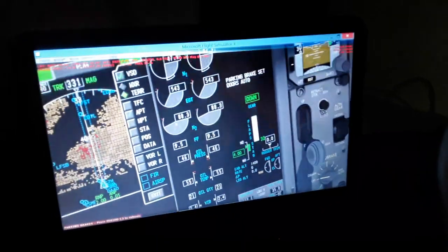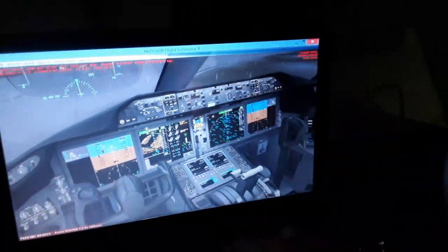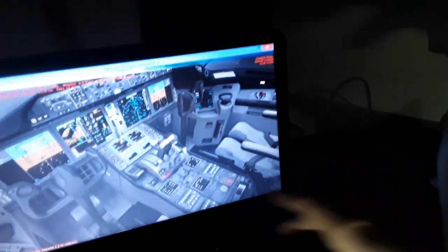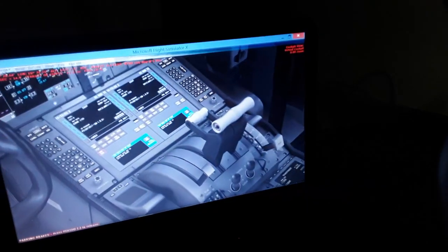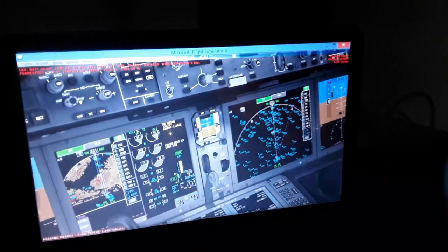The percentage of the thrust, exhaust gas temperature, and two, you can see the indications are controlled by the FADEC. When we move the thrust levers, we give a command to the full authority digital electronic control computers that control the engines functions of the Boeing 787 or other jetliner aircraft.